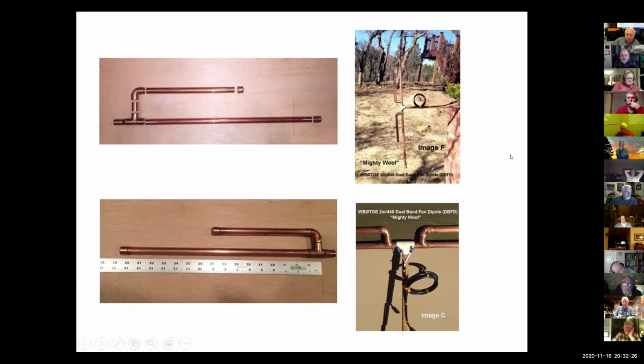There will come a point where the copper tube has gotten hot enough that it will melt the solder. You don't want to put the solder into the flame. You want to heat the copper pipe with the flame of the torch, but a little away from where you're actually going to be putting the solder into the joint.